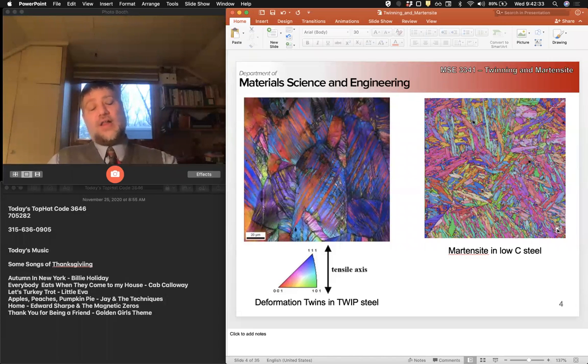So the active development in the 80s was essentially the invention of what's called YSZ, or yttrium stabilized zirconia, where you have zirconium oxide that is doped with yttrium to prevent that martensitic phase transformation. Okay, so exceptionally important in ceramic materials as well. I'm not aware of any polymer martensites, but there probably are.